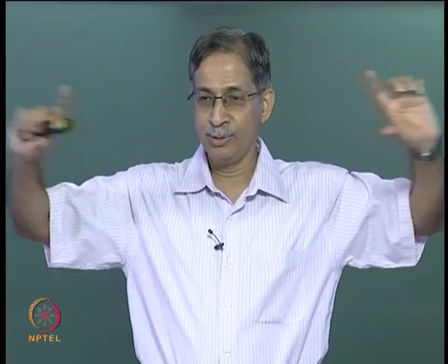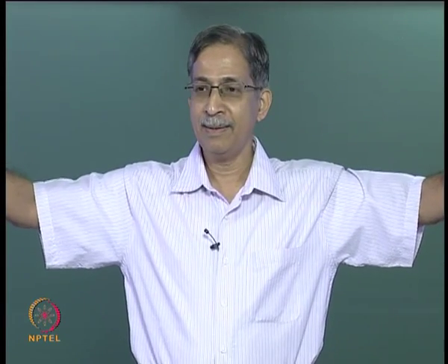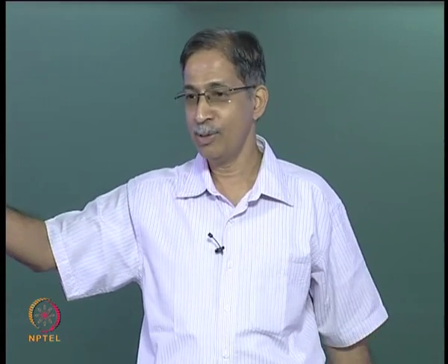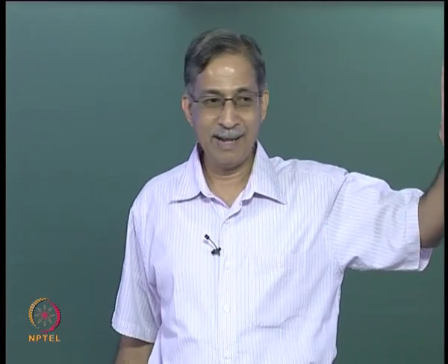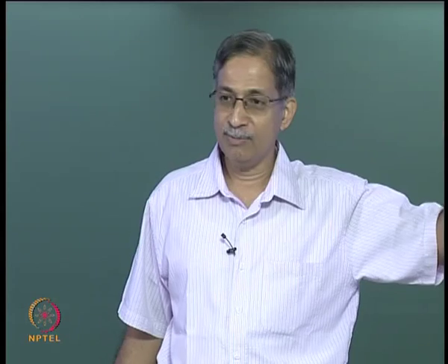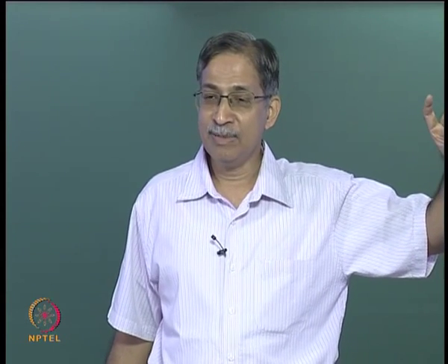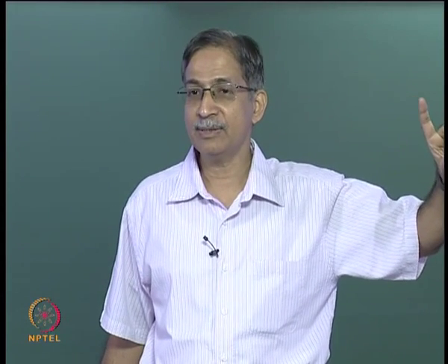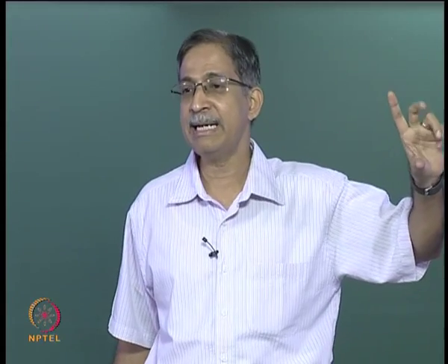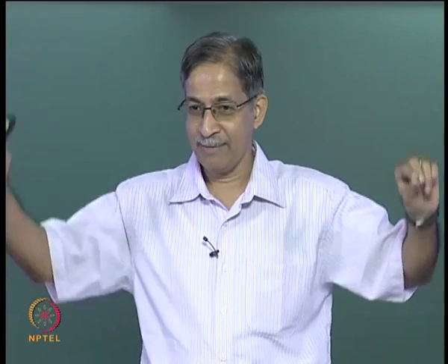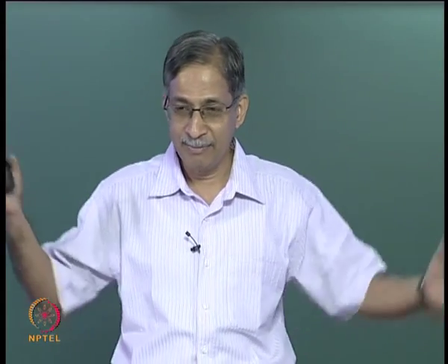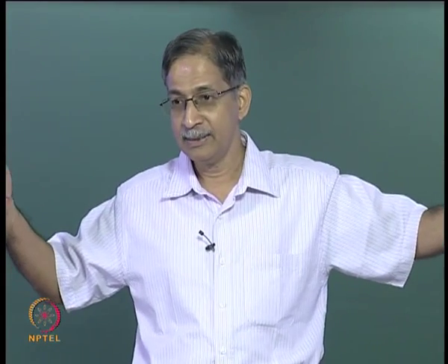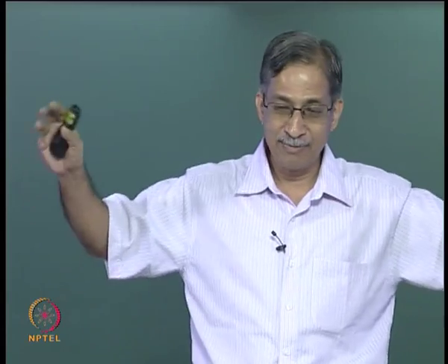So when you have a huge beam sitting on top of them, where you have the shear wall you won't get much movement, where you have the column you will get a movement, and that movement gets enhanced with time because in concrete we have a phenomenon called creep. So you have differential settlement in that beam, and if the beam is not long, 6EI delta by L squared is the kind of fixed end moment that you will get. That is a huge moment.